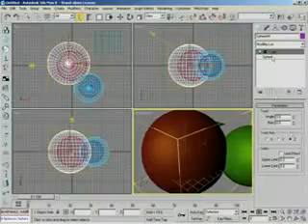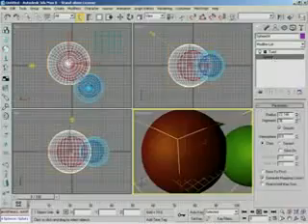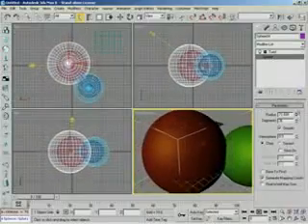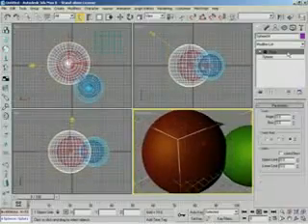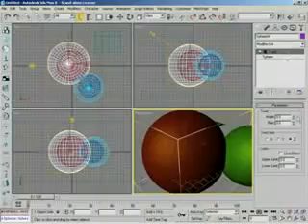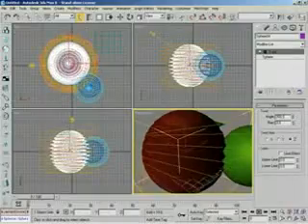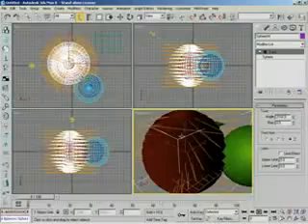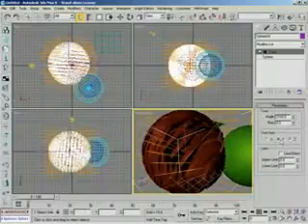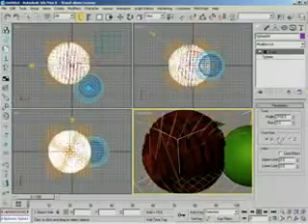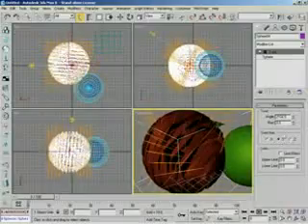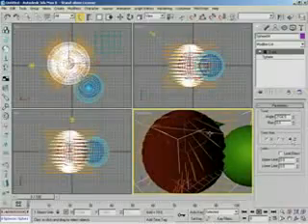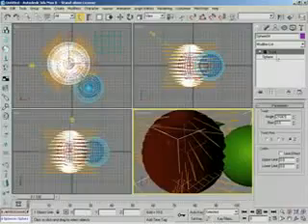So watch this. I can jump back in history to my sphere. I can still change its radius. Now I can step forward into the future where a twist was added. I can then come in here and start changing the angle. So now we have definitely modified the shape of this, right? And we can control which particular axis it was done on, and there's limits and all sorts of fun things that we can play with for controlling how this modifier will affect the sphere.